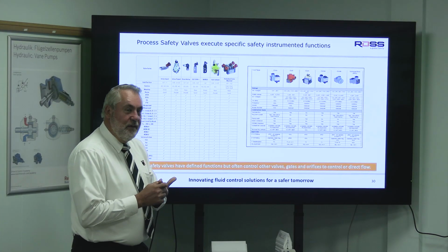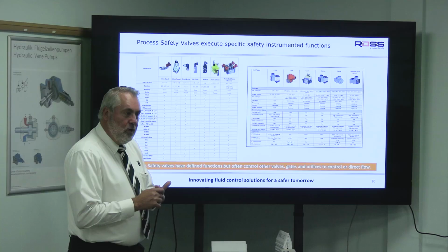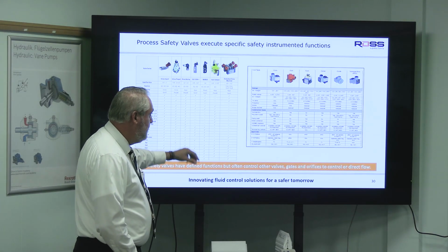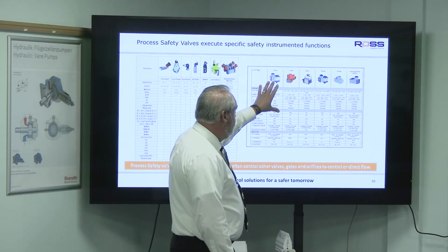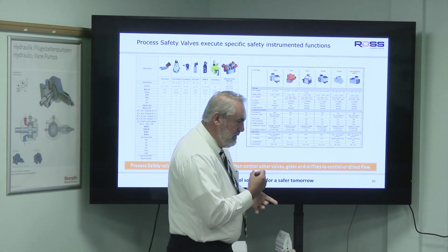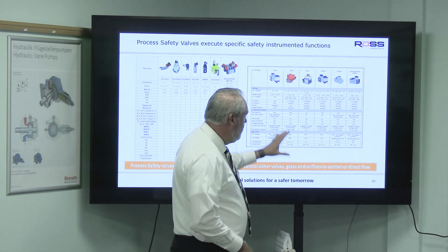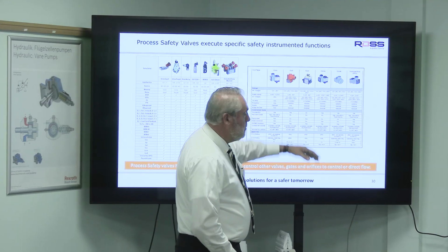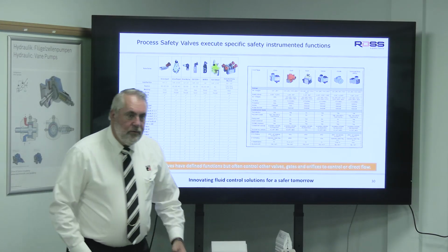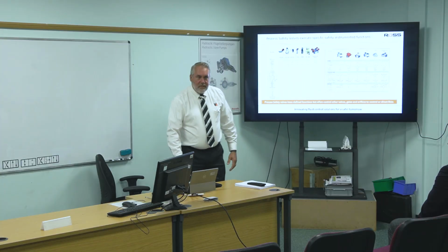So that's where we're using that voting system, because structures are different for process valves. And then we have different coil types, and those coil types either limit energy or they seal the coil, one or the other, depending on which coil it is. But these are explosion proof type coils. And so those are used a lot in the process industry.